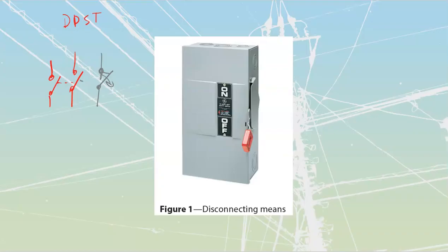Over here, the signal of operation. We'll just draw this out here as a circuit breaker. So I've got my breaker over there. We're then going to run this over to my isolating switch over here, and then we're going to run that over to my load over there. If I were to flip this breaker off, so I'm going to disconnect the breaker right now, at that point I would be able to open my isolating switch, and then I'm safe to work on whatever that load is down there.